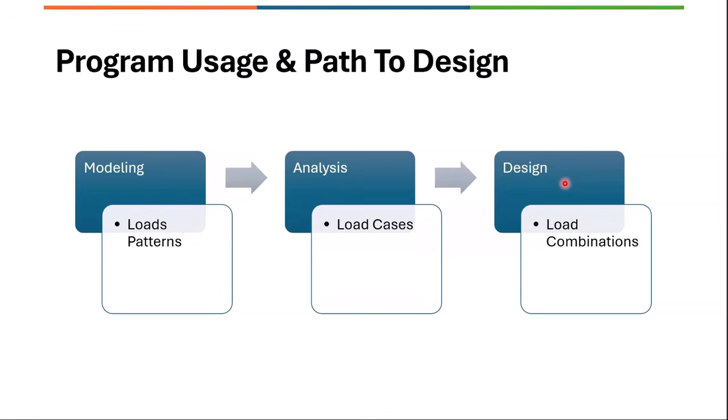And that information can be passed on to the analysis load cases. So the load patterns will have a load case automatically defined whenever you define a load pattern. And then these load cases will recognize the type as well. Once we perform the analysis, we'll get the results for each load case. Then we'll combine these load case results with appropriate load factors as per the code under the load combinations, whether it is for strength or serviceability.